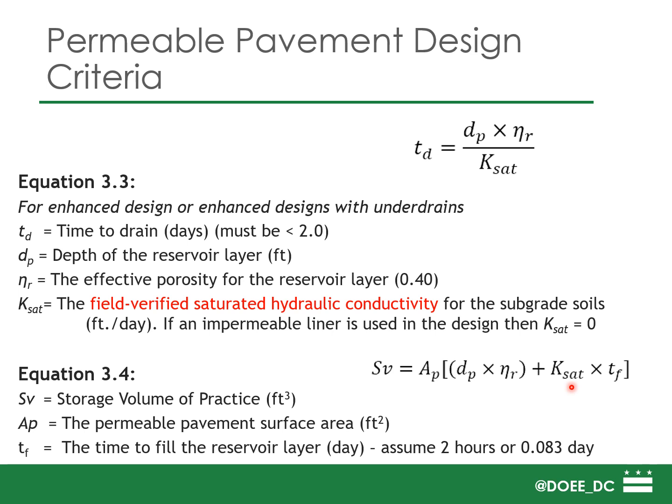The time to fill the reservoir layer is assumed to be 2 hours. This is a standard. In those 2 hours, whatever infiltrates based on the hydraulic conductivity is also considered in how much storage you achieve. So the storage is the static storage on the left here and the dynamic storage on the right, multiplied by the area of the pavement, and you get the overall storage volume for the practice in cubic feet.